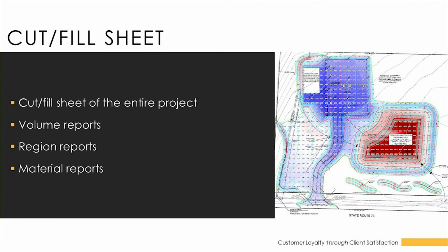So as you're looking at the map here on the screen, we can see a building that was cut out purposely, but around there you've got a parking lot in the very front on the south side. We've got a lot of fill just to get to basically the yard of the structure. Then off to the lower right hand side we have a big red area that's all cut. That's a detention pond. So this project was designed specifically to have no excess waste or imported material. It was basically a balanced site.